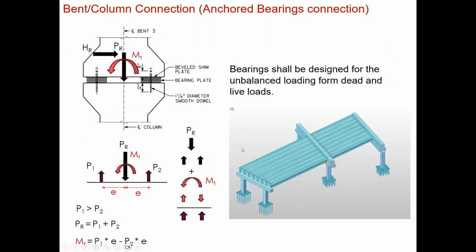If we think about the load transfer here and look at the end of the cap at the column, we have a torsional moment acting on the cap, primarily coming from live loads on unequal spans. In this case, the dead load can also contribute to the torsional moment on the cap. We have the vertical shear or vertical loading at the end, and we have lateral loads coming from braking forces, wind loads, all types of lateral loads on this cap.